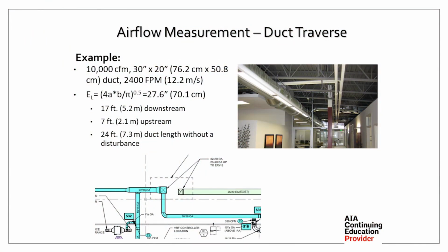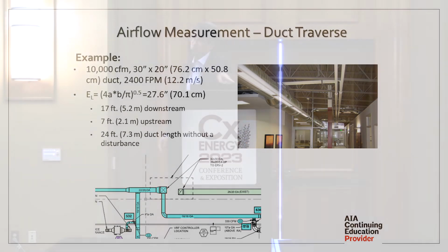Jim, yes? There's no longer a requirement like that for traverses. As long as you have a straight duct, you have 1,000 feet per minute, and you don't have any negative or zero readings in your traverse. We'll get there next slide.